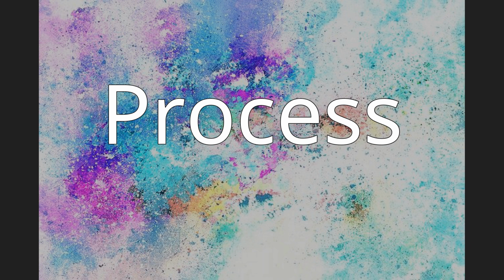Dye-sublimation. This process uses 4 panels of color according to the CMYK color ribbon. The card to be printed passes under the print head several times, each time with the corresponding ribbon panel. Each color in turn is diffused, sublimated, directly onto the card. Thus, it is possible to produce a high depth of color, up to 16 million shades on the card.